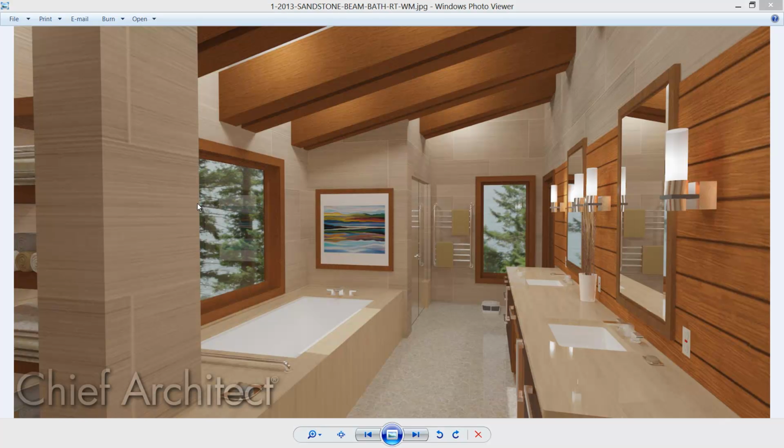The next step in the design is to create our tub and tub platform. You can see in a rendering here that our tub is inset slightly under mount and it wraps around the wall. So to create a custom tub platform, one, I could place a base cabinet and stretch it very long and insert it like you saw earlier in the video with the sink, or I can place a freestanding tub, so to speak, and then create the platform as you might actually do it in the field. So that's the approach I'm going to take for creating our tub platform.